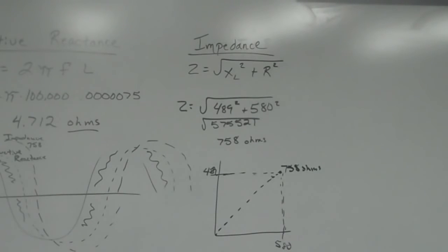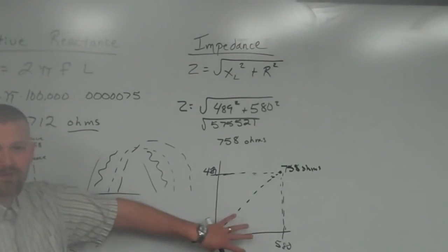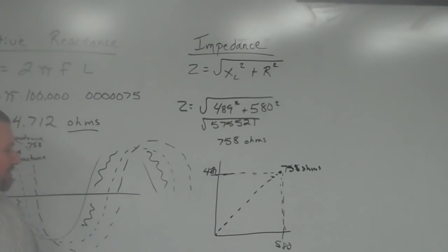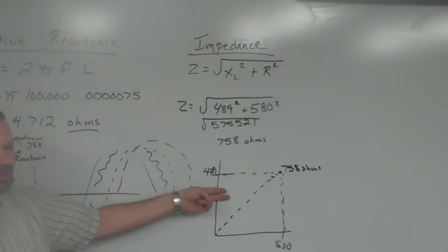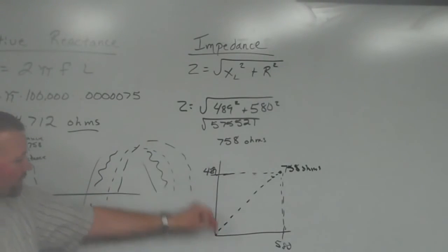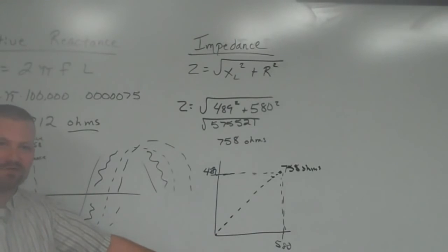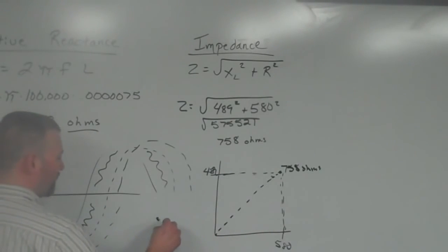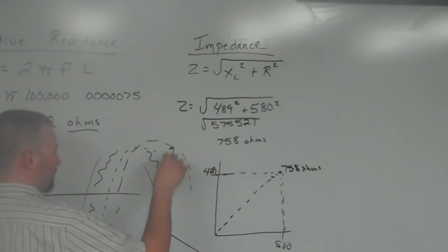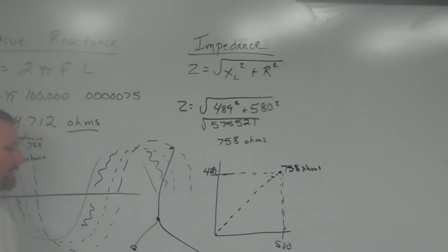Now what that actually represents to us right now is not a whole lot, except the next couple videos are going to be about movements, shifts, stuff like that. We're going to look at when you start off with the impedance of the coil in air, then you take the coil and put it down on something, the impedance is going to shift. So when you have a shift in the coil, you're going to have a shift, maybe from here on your screen down to over here, or up to here, or down over here somewhere. It doesn't really matter, but we're going to look at the difference between those shifts.